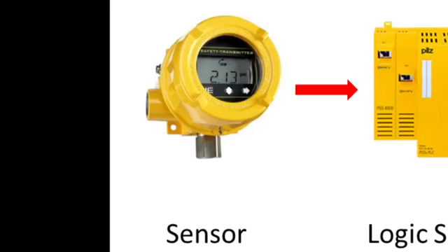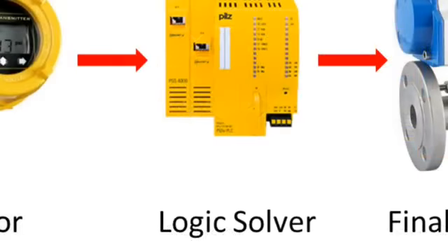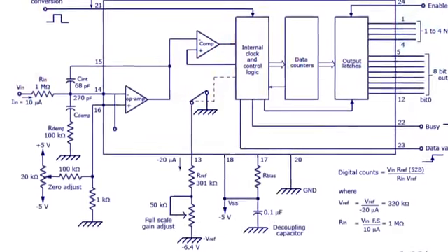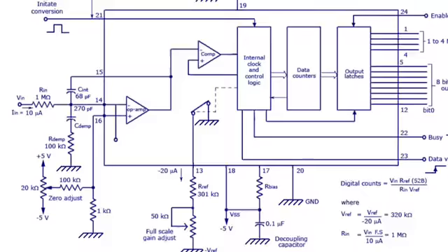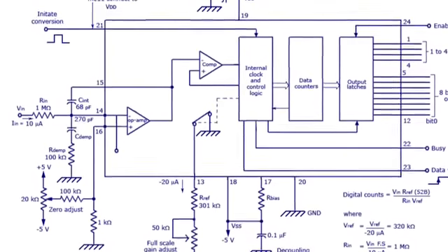For example, the sensor component must continuously monitor the process variable and provide this information to the safety PLC via a hard-wired connection. What actually occurs, however, is the analog signal from the sensor transducer is converted to the digital domain for processing.